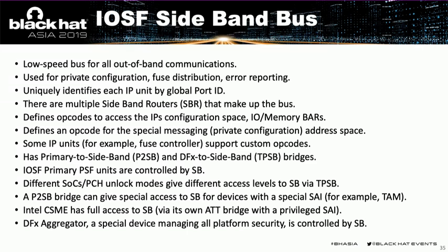Inside the sideband bus, each device is globally identified by a so-called port ID. Also, for each operation, the IOSF specification defines an opcode. There are opcodes to read and write configuration of every device, to access its BARs, and to access a private device configuration not accessible via the standard PCI Express PCI configuration header.